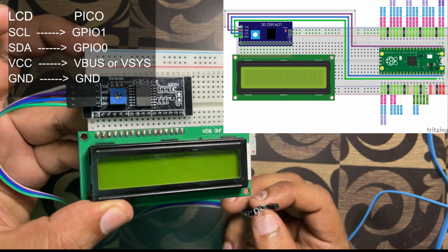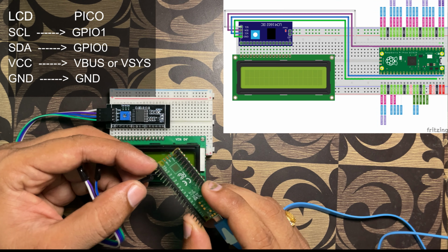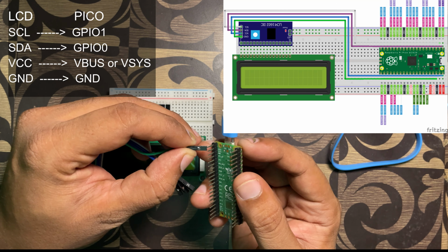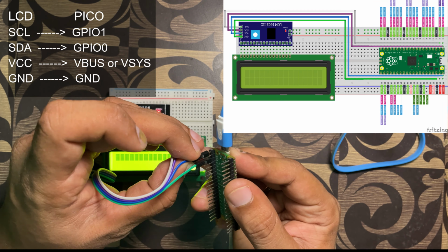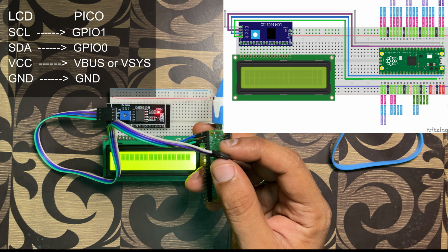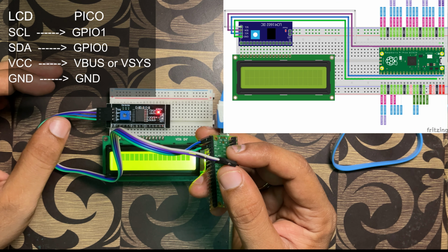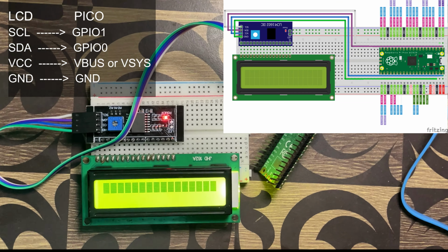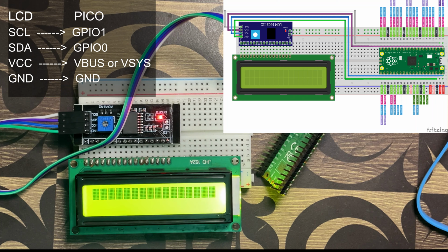As we discussed earlier, SCL pin to GP1, SDA pin to GP0, VCC to VSYS and ground pin to ground. And that's it. This is all about the connection.